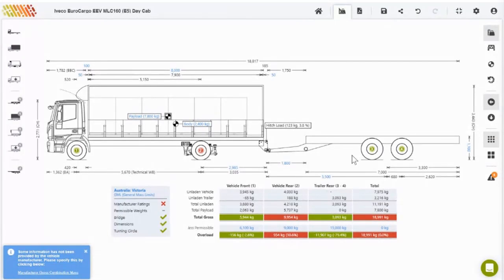But there's a quirk in the exemption that we get for Victoria, and this is where the engineering side and Ben's experience all come together: the only trailer that you get the exemption for is a semi-trailer. So if you've got one semi-trailer, it doesn't work for B doubles, but if you've got one semi-trailer on, then you get your 17 tonne on your tandem drive. But if you put any other trailer on, even single drive tandem, then you lose that exemption.